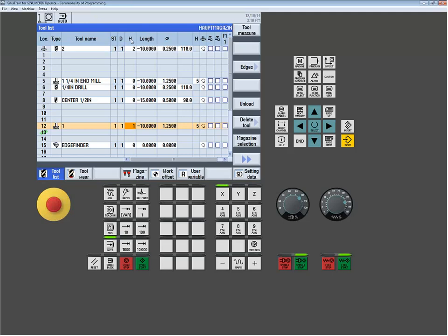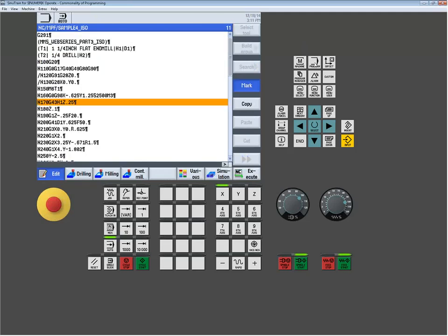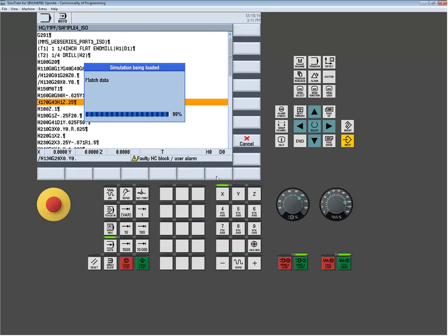It's also a quick way for you to know if your control supports this ISO mode. It's not an option within Siemens, but it's up to the builder if they want to commission the machine that way or set up the control that way. If you do not have an H column, your system does not support ISO, and everything we're talking about now cannot be done. It could be turned on, but you would have to put a request in through the OEM on that. So now by adding my H values here, I can simply go back into the program, simulate it,